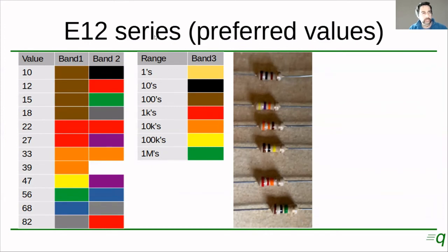So if you get used to reading resistors, you don't have to read them one by one because these numbers that we have here are like words. Once you understand that not all values are possible or very common, you can probably read the most common values very, very easily and very, very quickly. For instance, this one here is a 100 kilo ohm resistor or 100K. And I just know it. I see brown, black, yellow, and I know it's a 100K resistor.